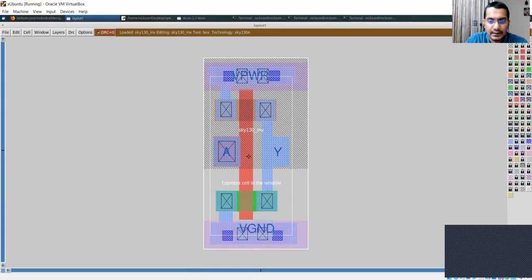The first thing to notice over here is the non-planar surface topography. The surface topography that you see over here is completely non-planar, and it's not a very good idea to deposit the metal interconnects on this layer. There are some problems with respect to metal discontinuities and so on. We'll talk more about that when we get there. But the bottom line is, you can't use this surface topography for your metal interconnects. What do we do about it? The best step is to planarize this particular surface. So how do we do it?